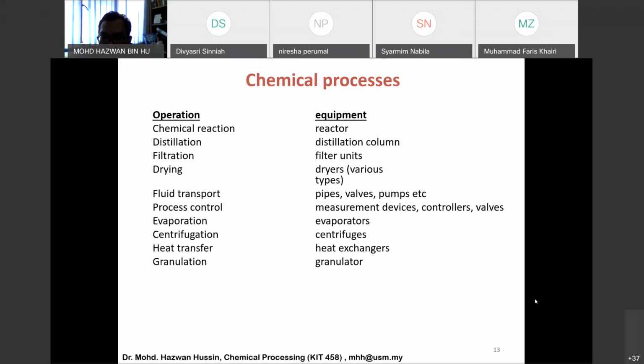If you have a mixture of alcohols, you have methanol, you have ethanol, and many things inside. Each and every chemical has its own special boiling temperature or vaporization temperature. Then you can actually use distillation to isolate the solvents individually.